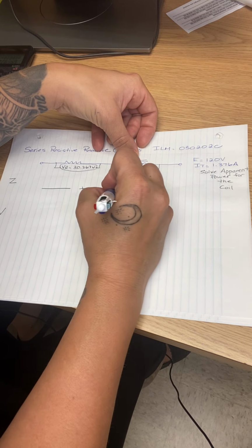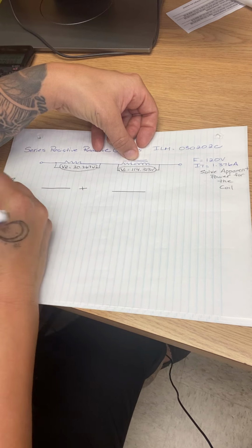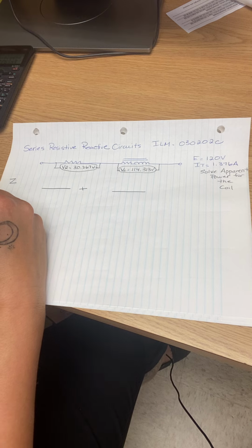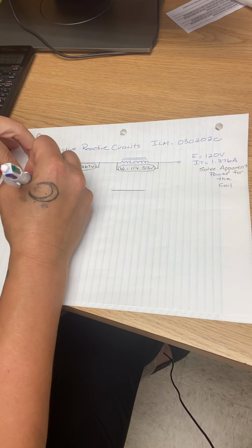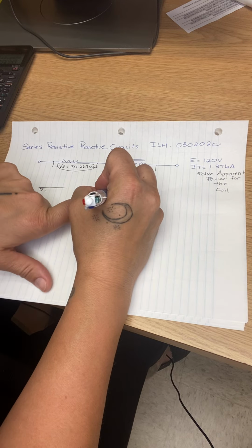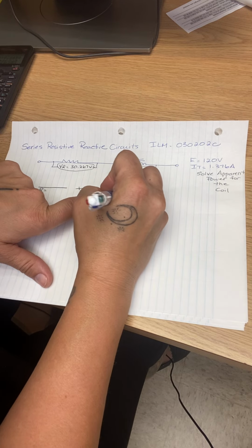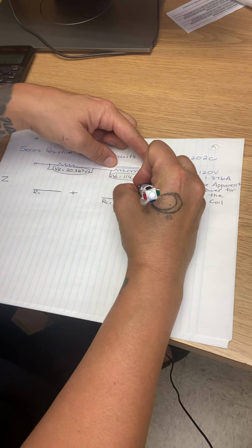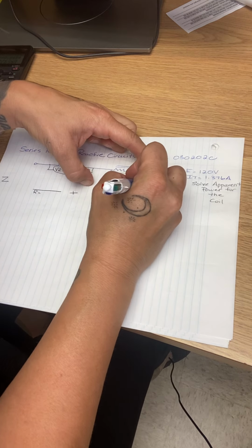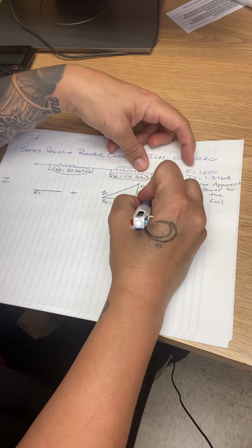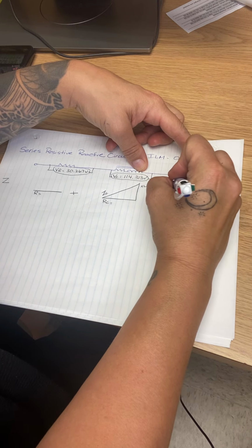So the coil has a variable of in-phase resistance in it. It is a component that is constructed of copper, many turns of copper wire. Therefore, it is going to have a variable of resistance in it. So first of all, that would be my R of the resistor. Then the coil has a resistive component. I'm going to label that RC, the resistance of the coil, as well as it's going to have an XL component because it's an inductor. And then the vectorial sum of those two sides would give me the impedance for the coil. And then this over here on the right-hand side would be my circuit totals.